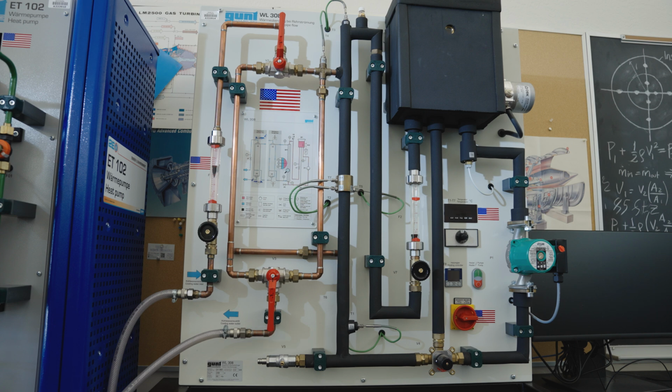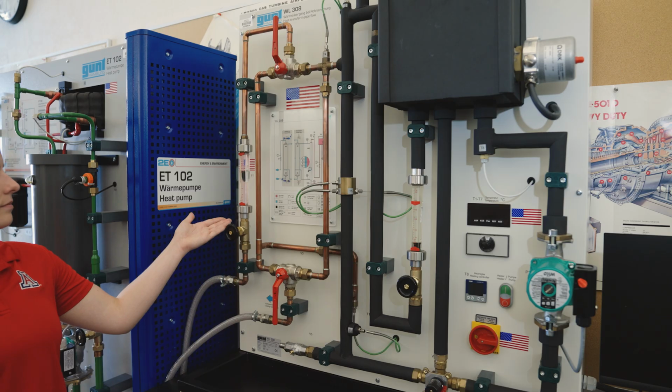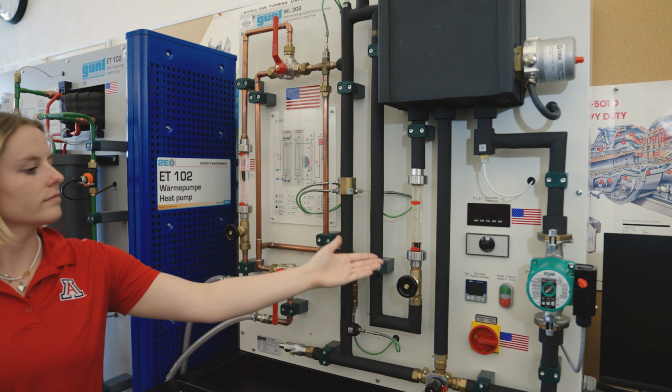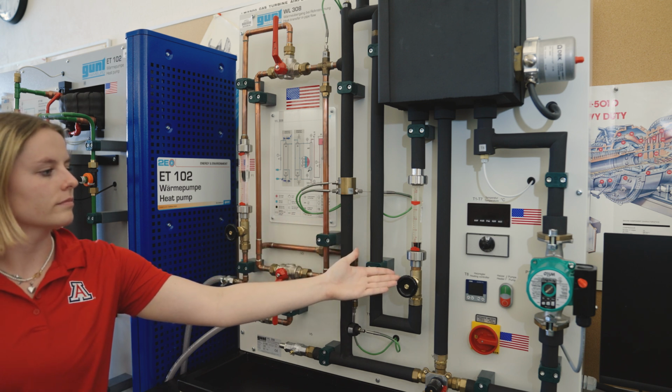Parallel flow is achieved when both the inner and outer flows run in an upward direction. The counterflow configuration is achieved when the cold water flowing in the outer pipe runs in a downward direction. The heat exchanger pipe is equipped with temperature sensors that measure inlet, outlet, and midway temperatures of the fluids, as well as the outside wall temperature of the inner tube. Volumetric flow controllers allow the adjusting of flow rates of both cold and hot flows.